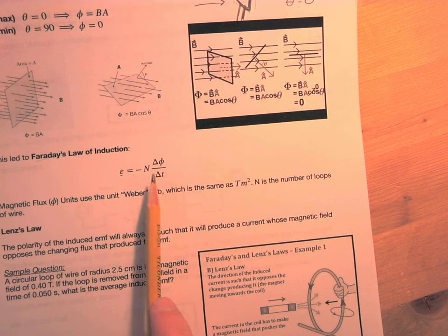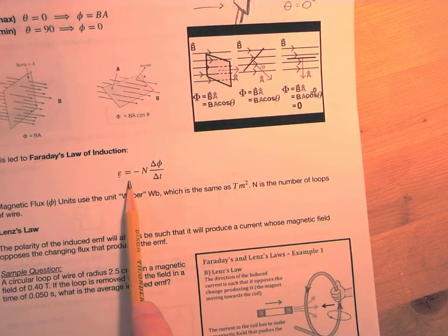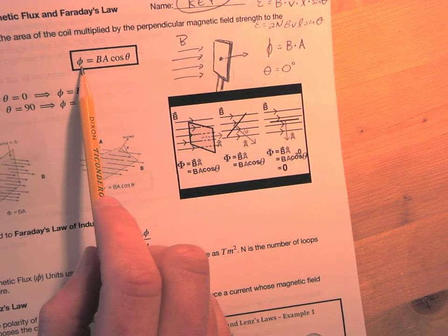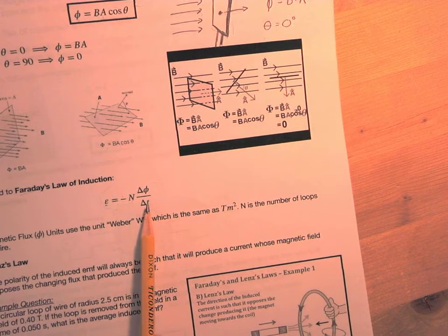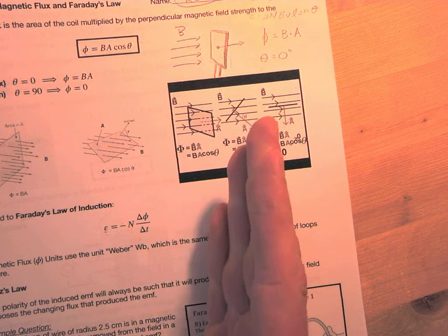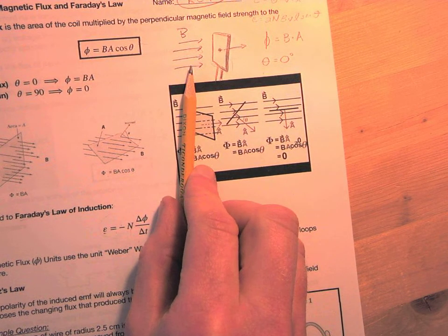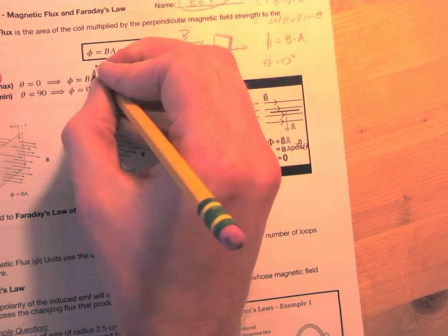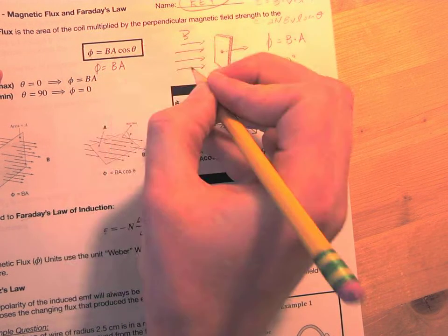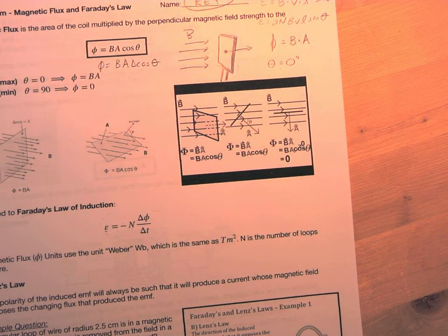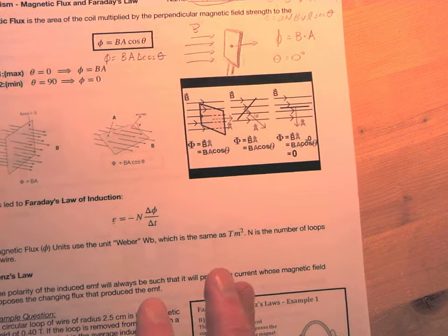But in this case, you can find it another way, still the same thing, by going the number of wires times the change in flux, which is this, over the change in time. Okay, so it's kind of the change in the area in relation to this magnetic field over the change in time. Okay, since it has a cos theta, you can kind of think of it as phi is equal to your B times your A times the change in cos theta. Just when it's turning like that, you can kind of think of it like that as well. So you know it would go in between BA and 0 as it spins.